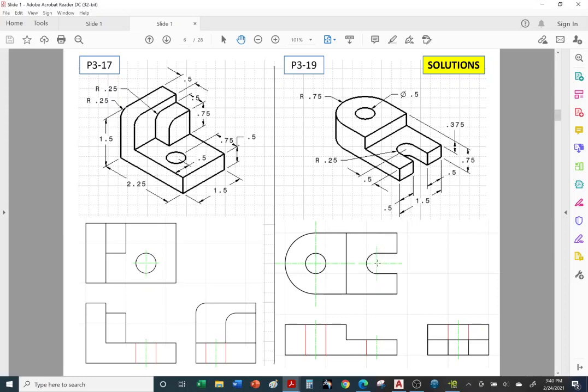Locate the center. The reason we need to locate the center of a hole or semicircle is because when a machinist drills a hole, so when they drill this hole, they're going to aim for the center. So they need to know where the center is. So it's important to dimension center to center, and we'll cover dimensioning measurements in a later chapter.